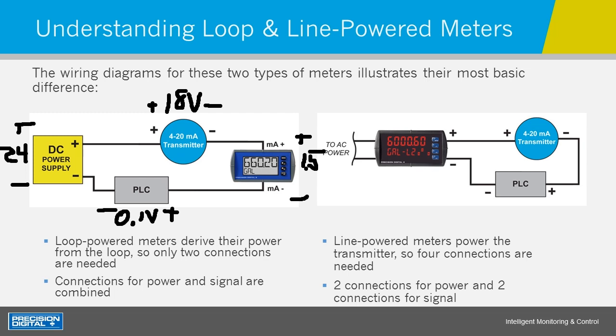Now in this case, I've got 18 volts plus my 1.5 volts plus some tiny amount for my PLC. So I'm under 20 volts in total voltage drop, and I'm driving it with a 24 volt supply. So I have not only enough voltage to run the loop, I have plenty of overhead as well. I've got almost 15% to 20% overhead before I reach my 24 volt max. So I have plenty of voltage to run this.